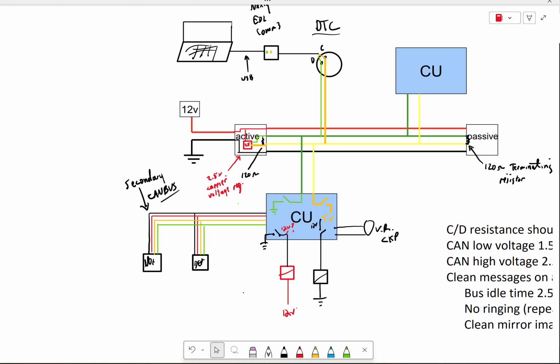But for the most part, in terms of monitoring how much NOx is in the exhaust and then dosing accordingly, and then monitoring how much we have after it's gone through the SCR catalyst, we don't need that information on the instrument cluster. It's completely irrelevant. So why clog up the main CAN with all of that messaging? Why not just leave that to its own separate CAN network? That's why we do this, okay?